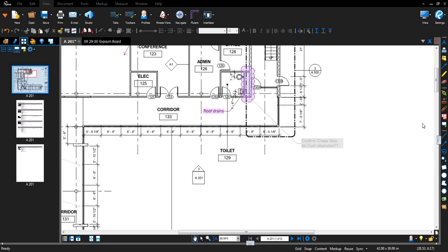the tools. Now, one of the key questions we do get quite a bit is whether the markups that you're placing in Revu work similar to the markups in Autodesk Design Review. The markups in Revu are PDF markups, and in order to get back into AutoCAD, they do have to be imported as an XREF file. So they don't come natively back in like in Design Review.